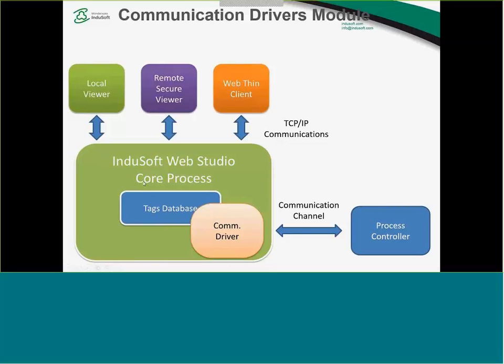So the core process of the product is the one that's going to spread out that information, and through TCP/IP it is going, for instance, to reach the local viewer, the remote secure viewer, or any of the web client options. So the driver here is the one getting the data and pushing the data to the tags database. You don't see the driver talking to the screens. The driver is going to push to the core process. The core process is the one that's going to distribute this information out to all the visualization modules.